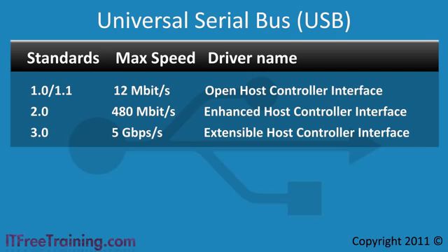Regardless of what devices you buy, you can plug in the USB device. Your computer or USB hub will work out the speed of the device and match the speed. In other words, you could plug in a USB 1.1 device into a USB 3.0 port, and the speed will automatically drop down to USB 1.